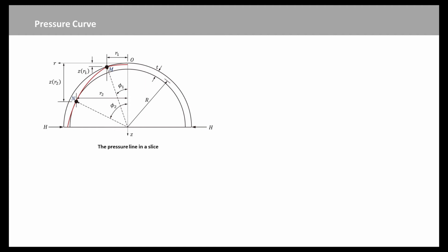This state is so characterized that the thrust surface is all contained inside the dome, and the extrados and the intrados of the dome will be touched by the thrust surface along two circles corresponding to the two internal hinges of the collapse mechanism. This figure shows the two hinges of the mechanism formed at points M and N.